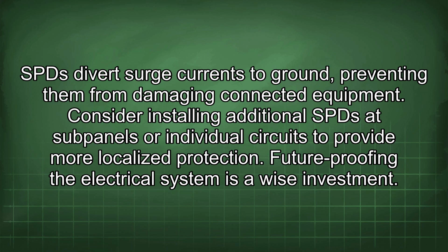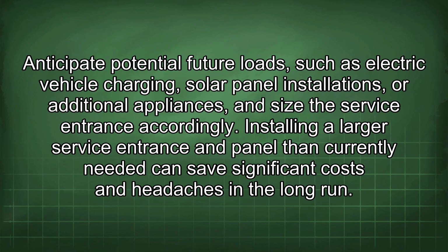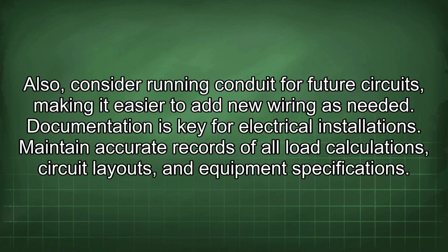Future-proofing the electrical system is a wise investment. Anticipate potential future loads such as electric vehicle charging, solar panel installations, or additional appliances, and size the service entrance accordingly. Installing a larger service entrance and panel than currently needed can save significant costs and headaches in the long run. Also, consider running conduit for future circuits, making it easier to add new wiring as needed.